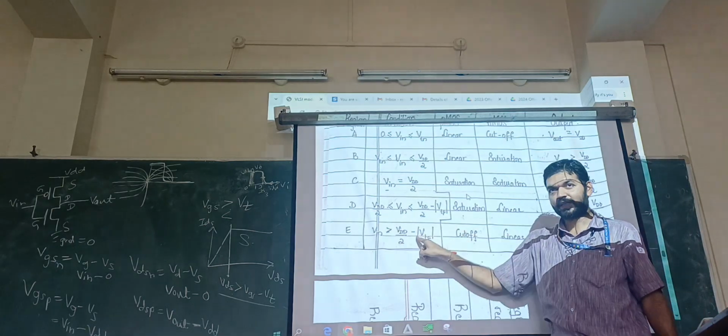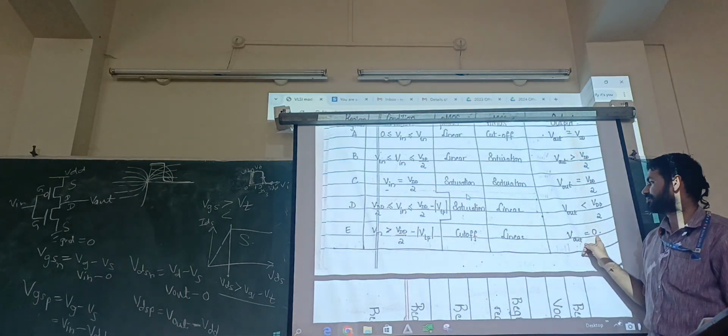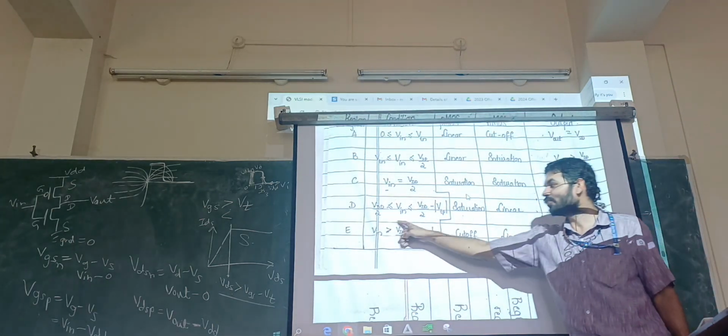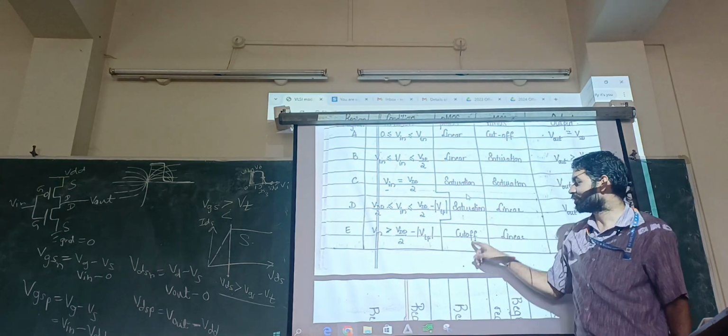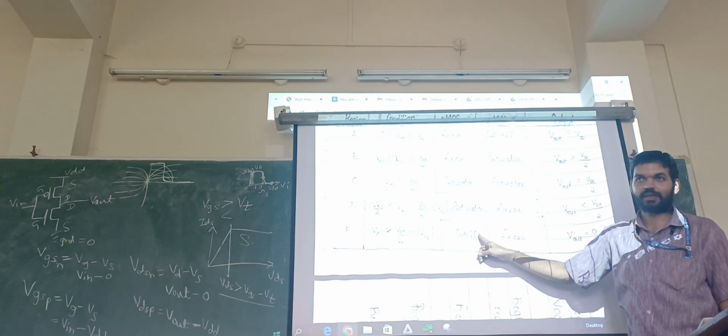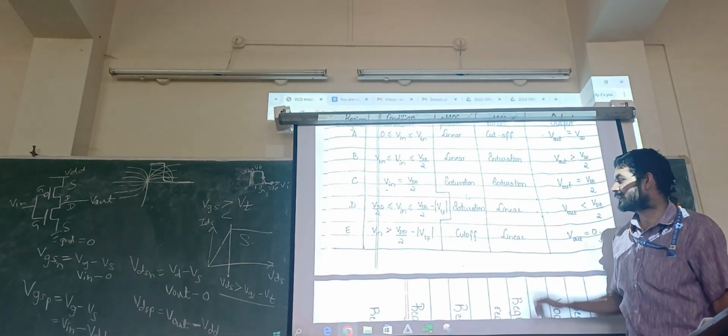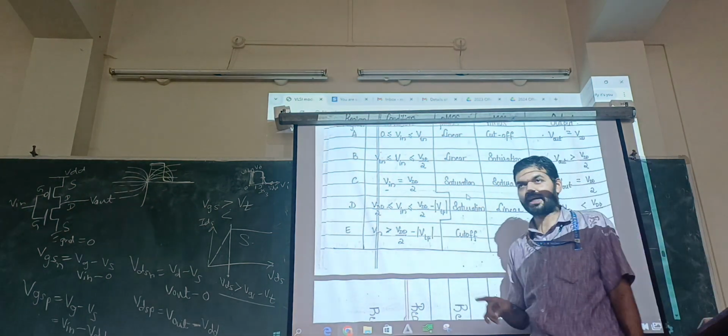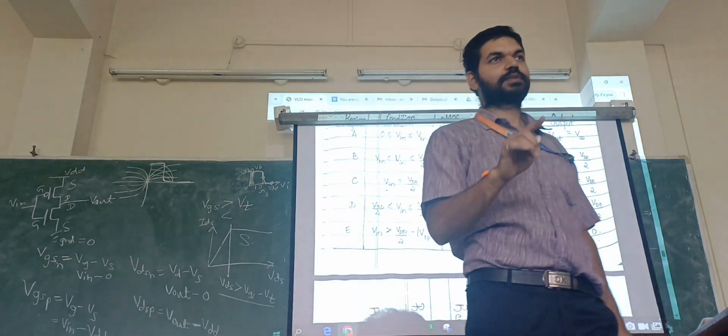Input is near 1, output is 0. Therefore, PMOS is off. Okay, so this is all about DC transfer characteristics of CMOS inverter.